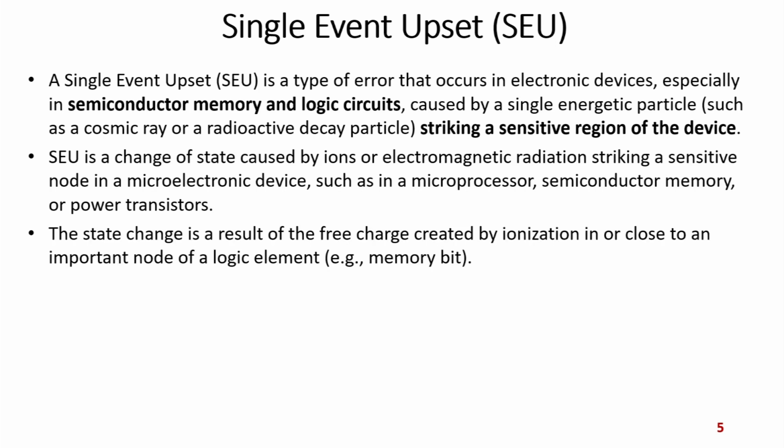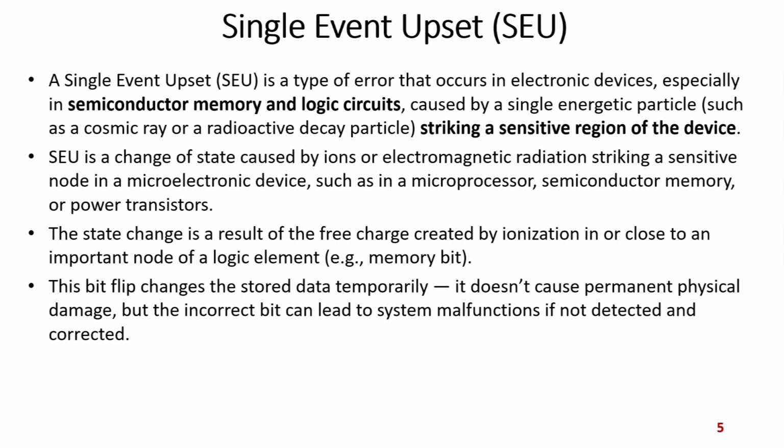The state change is a result of the free charge which is created by the ionization inside or close to an important node of a logic element. It can be a memory bit. Because of this there is a flip in the bit, and though it is not permanent, it can temporarily malfunction if it is not detected and corrected.